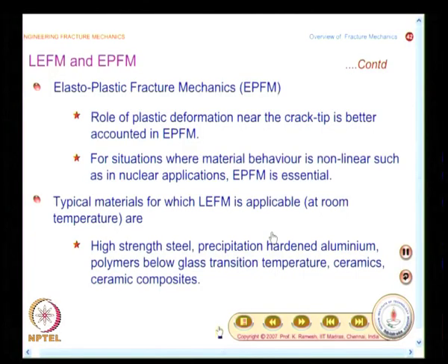You could also classify LEFM and EPFM based on which material you are dealing with, and I would like you to take down the notes of these slides. When you look at LEFM, if I use high strength steel, precipitation hardened aluminum, polymers below glass transition temperature, ceramics and ceramic composites, for all of these materials you could comfortably go and attempt LEFM.